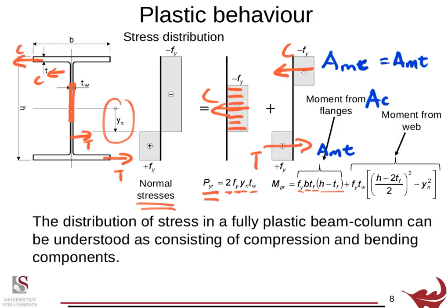So you can then start applying this to asymmetric, well, singly symmetric sections and the likes, just by finding a sum of forces to carry the moment, and then the area in the middle carries the compression load.